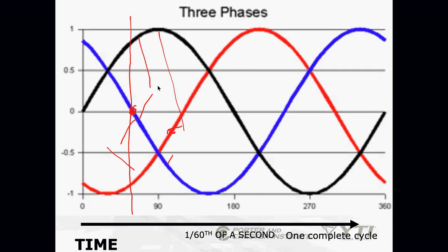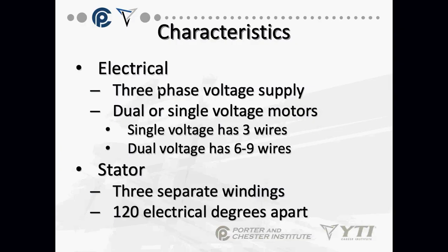Yeah, I'm always going to have magnetism on the winding because I'm always going to have a winding with AC power going through it. That's the whole premise of three-phase motors. You always have magnetism in the windings. There's never a point in time where I could have a collapse of the magnetism. So the motor's constantly getting power. A three-phase power supply has to have it. I can't use single-phase power on a three-phase motor.